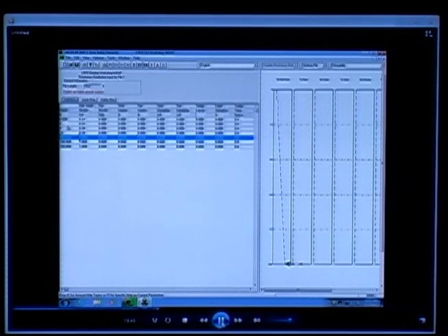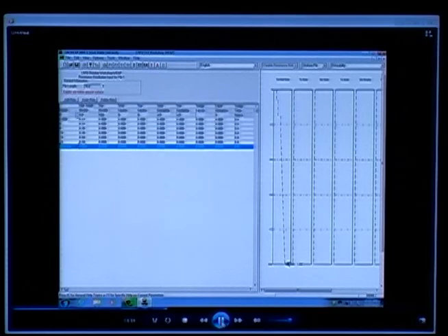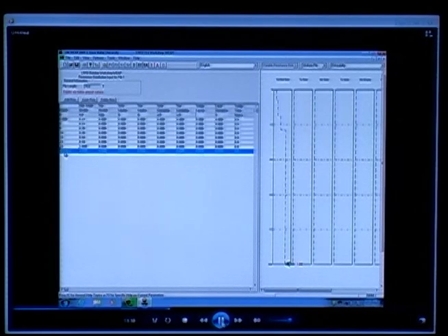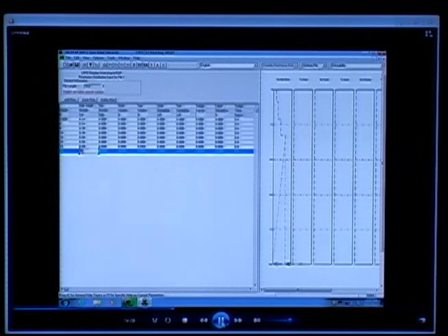The third layer from 15 to 23 feet is a firm glacial clay. The unit shaft resistance is determined to be 0.58 kips per square feet. And the fourth layer from 23 to 88 feet is also a firm glacial clay. The unit shaft resistance is determined to be 0.96 kips per square feet. Note that the shaft resistance distribution at each layer is assumed to be uniform.